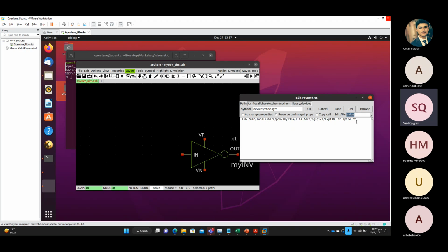Let's say the channel resistance is 10 kilo ohms, but it could vary a certain percentage, right? But the majority of the devices would have a mean value of 10K, maybe going up to 15K and as low as 5K. But very few devices would be at 15K and 5K. So therefore, when you simulate, you would simulate with a typical behavior. So TT is the typical.